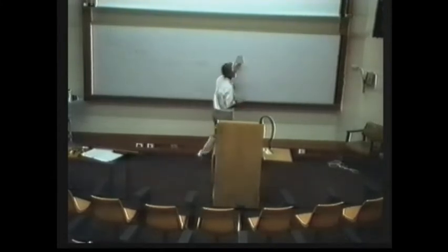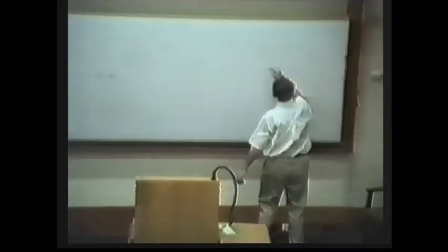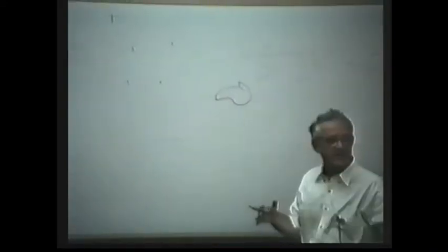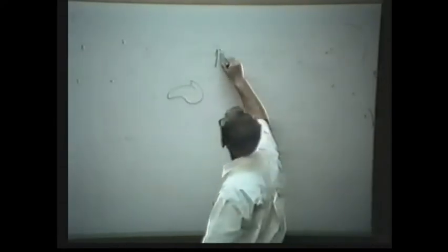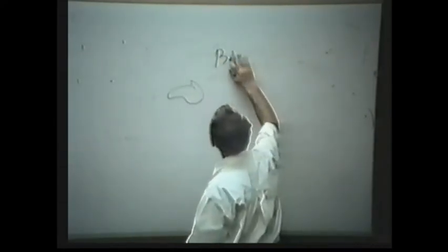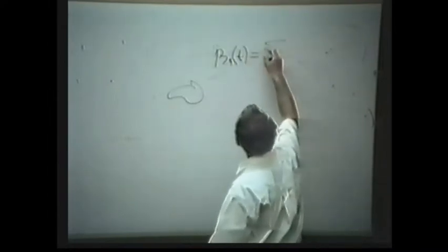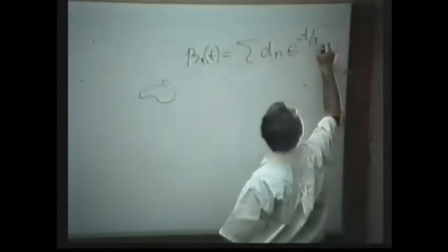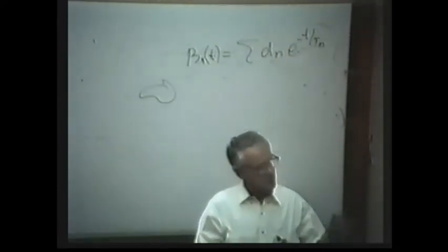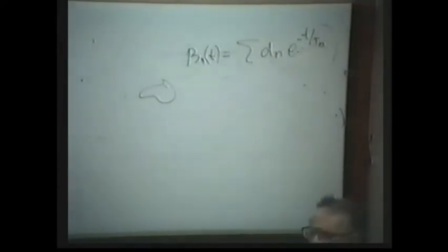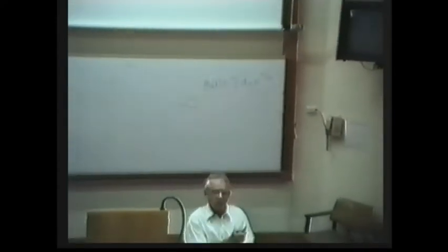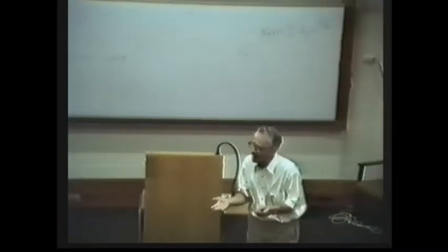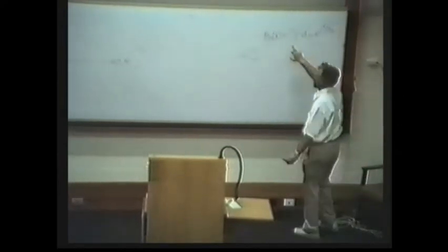Let us move a little back. When we considered a conductor in free space, the time response as a function of time can be presented as a sum of coefficients times exponents, d_n e^(-t/tau_n). That's typical behavior of currents in a confined conductor, and the field caused by these currents is described by a sum of exponents.